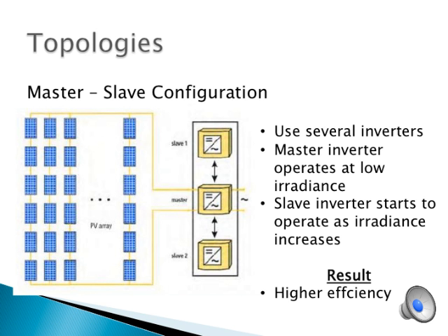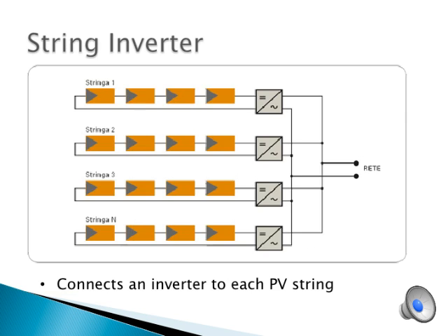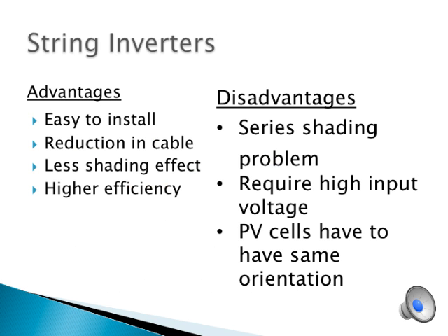I will talk about different inverters being used in photovoltaic applications. The first inverter I will be talking about is the centralized inverter. The configuration is really simple. All the strings are made up of PV modules connected in series, then strings are joined together in parallel connection. The main advantage of the centralized inverter is the low installation and maintenance cost, mainly due to the simple configuration.